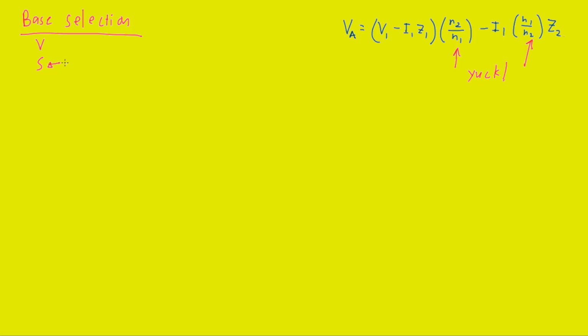The choosing of a base is a significant and pretty difficult element, actually, in the per unit method. On the PE, often the choosing is done for you, or you have a limited amount of choices to make. Most people taught the per unit method are told that they have many choices and a broad range of options to employ while doing it. But keep in mind, for a PE specific problem, you'll be forced into making choices which obviously yield the specifics of the correct multiple choice option.